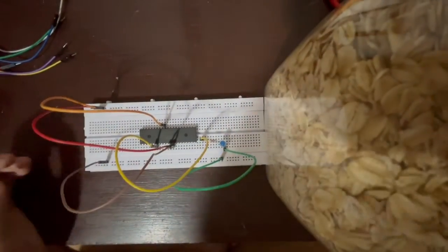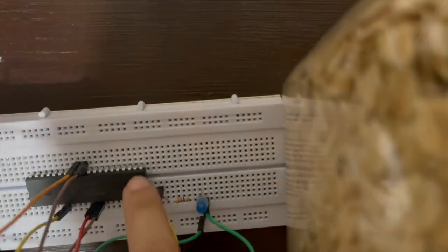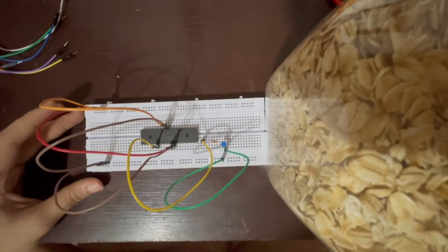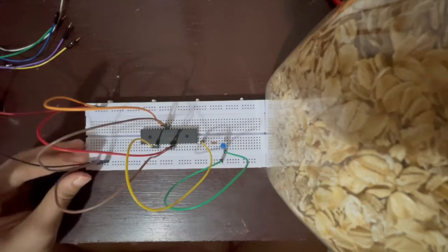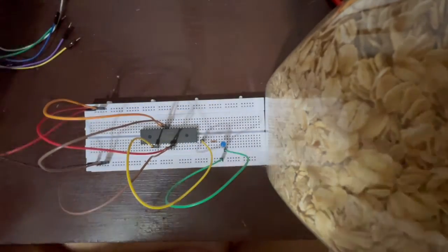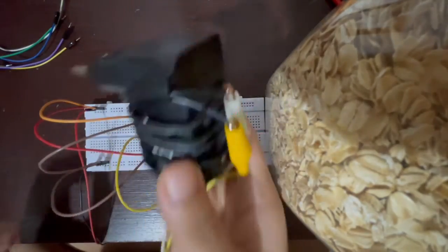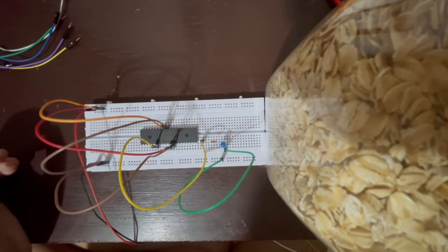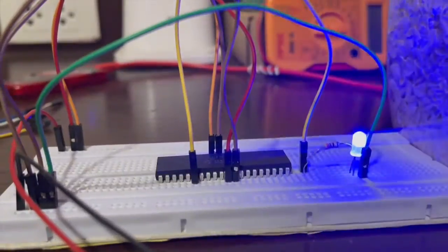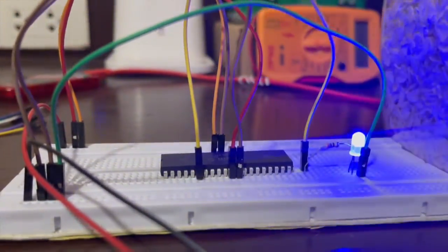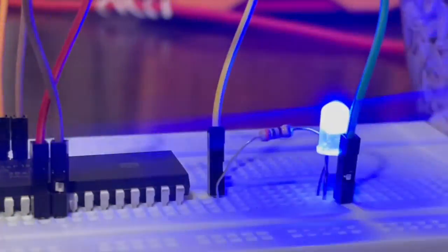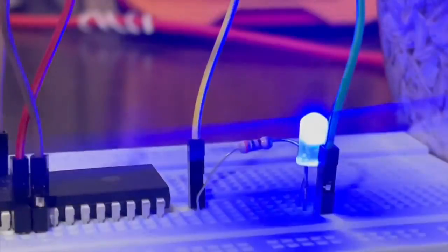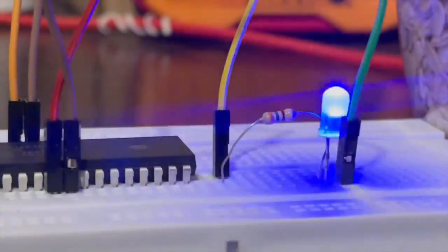also the VSS, pin 31, to the negative side. After that, connect the positive and negative terminal for the power supply and turn it on, plugging it in. After plugging it in, the LED is observed to light up for 250 milliseconds. It can be observed that the program worked, or the code worked. It was successfully programmed into the IC.